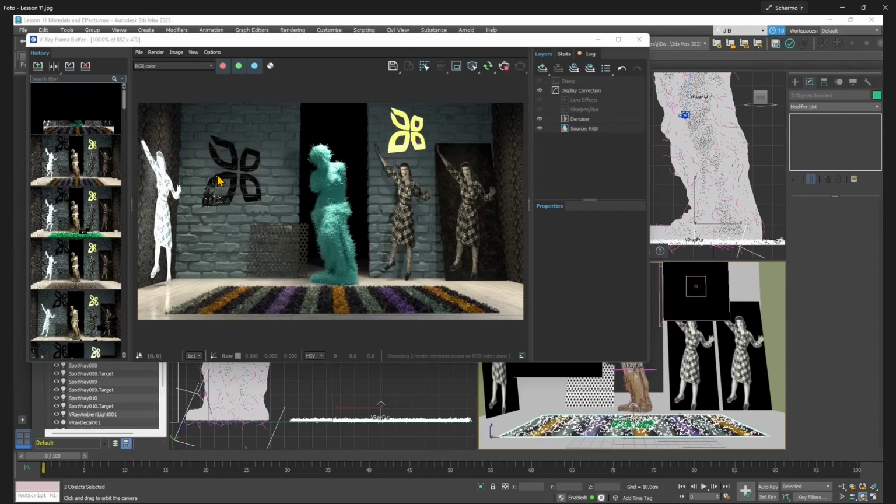So we discover that many effects for materials are gonna create a more realistic look to your scene, but also they're going to be heavier to render, like the carpet here with the hair and fur and the statue with the hair and fur there. But other effects like opacity will help you to optimize your scene and make it less heavy, like the opacity channel and the bump or the normal. So you need to decide whether to use heavier effects or lighter effects depending on the need, depending on your scene.